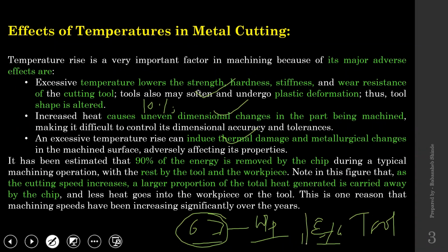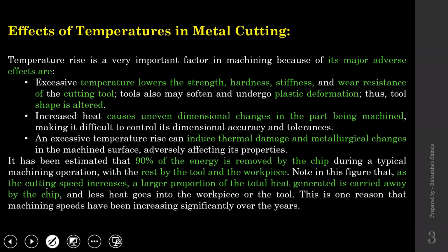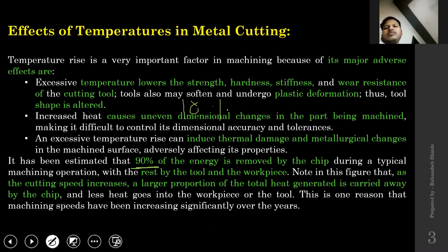Or I think this value will further drop by some digit. Okay, because minimum heat will be absorbed by the cutting tool, then the workpiece, and then the chip. Okay, now 90% is taken away by the chip, the remaining 10% is going to be absorbed by the cutting tool and workpiece.